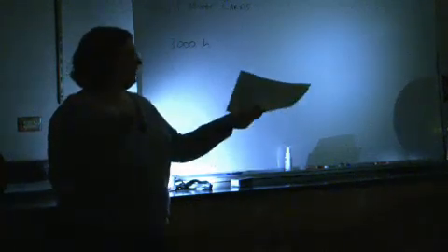But I bet other people didn't make the same assumption on the size of your solar panel. So what were some other assumptions and answers? Yeah. Well, we assumed our solar panel would be a quarter size of the smaller solar panel that we used last week. Then we also assumed that only 20% of that solar energy from the panel would actually be converted into chemical energy for battery storage. And subsequently, when we calculated everything out, it was around 3 hours total.